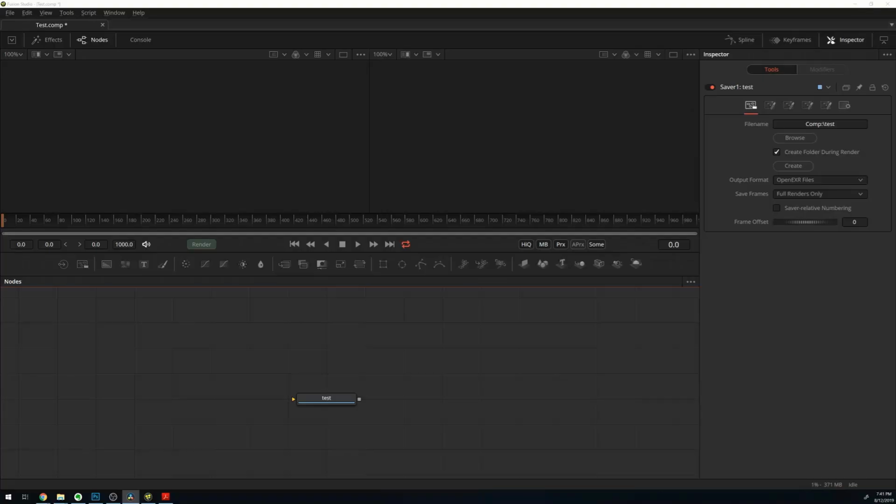In Fusion Studio you have here dedicated buttons for this. For these dedicated buttons, you also can do a right click on the proxy and auto proxy, and when you do it you see the level of the proxy resolution and can select it. So if I put it to 3, then it means that for the proxy each 1 in 3 pixels is being calculated while the proxy is on.